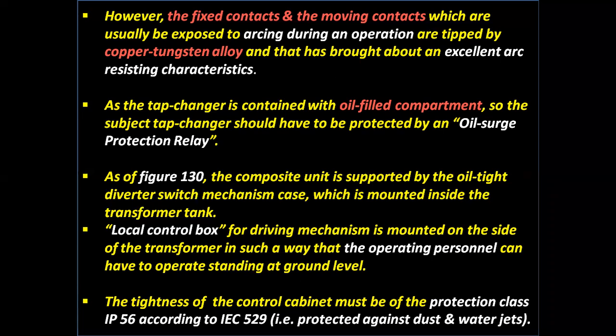The tightness of the control cabinet must be of protection class IP56 according to IEC 529, that is, protected against dust and water jets.